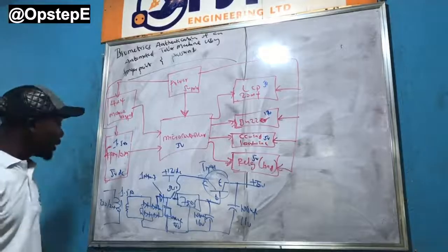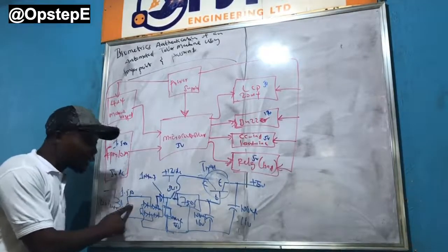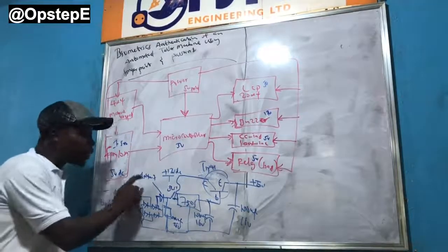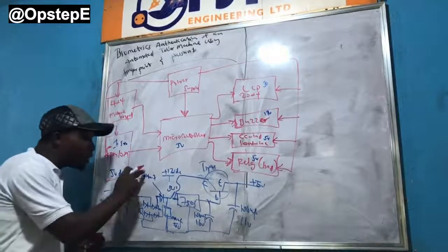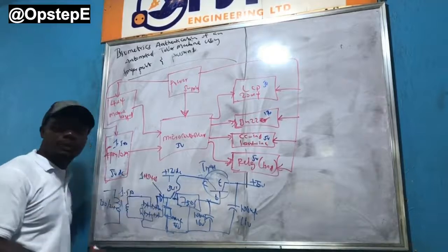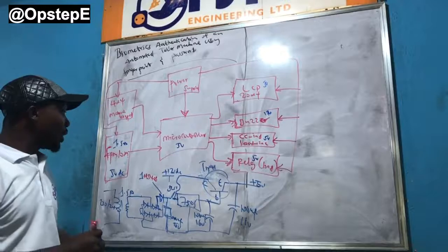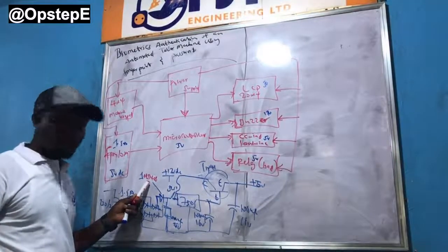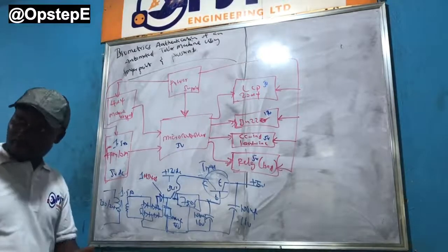So if you want to take advantage of the 1.5 amps that this transformer is set to deliver, then you have to change this diode to a bigger one. The next one you could use would be the 1N5408. Is it 58 or 54.8? 5408. This one can stand up to how many amps? 3 amps. Thank you very much. Does it make sense?